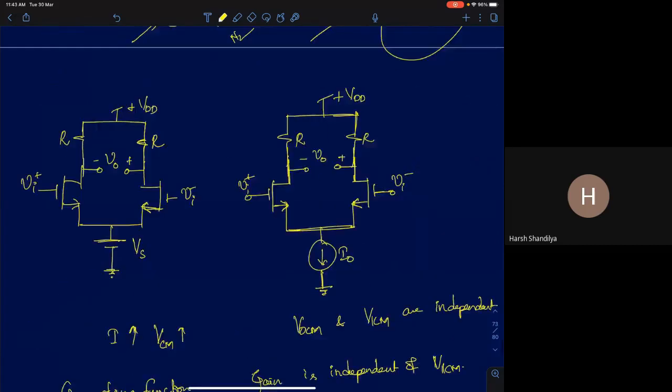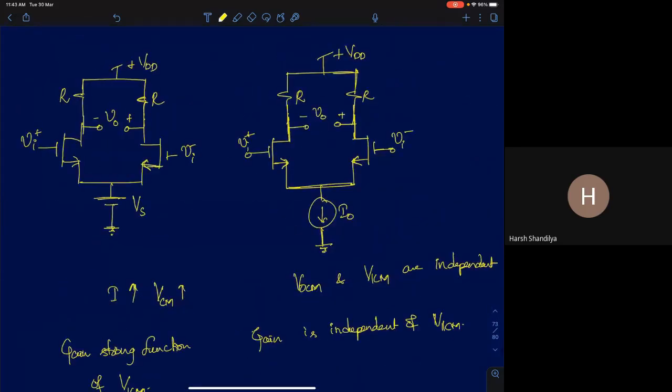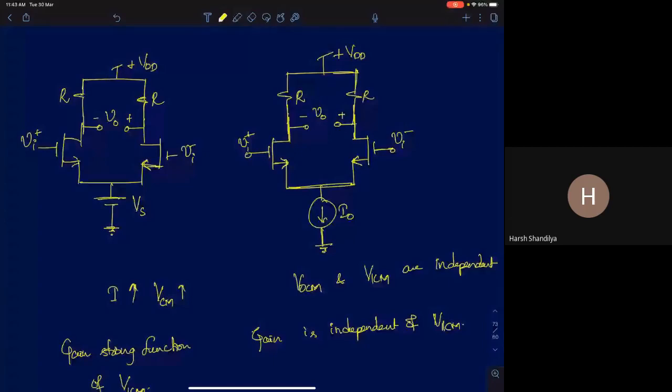Okay. So now the next one, we discussed large signal response of differential pairs to common mode and differential inputs. First I discussed how a differential pair responds to large signal common mode inputs. When I'm applying a large common mode change, for a voltage bias circuit, since the source voltage is always fixed, your gate to source voltage keeps increasing if you increase both the gate voltages, so your bias currents increase. If bias currents increase, then the gain also keeps changing in the circuit. So that's how this circuit responds to large signal common mode inputs.